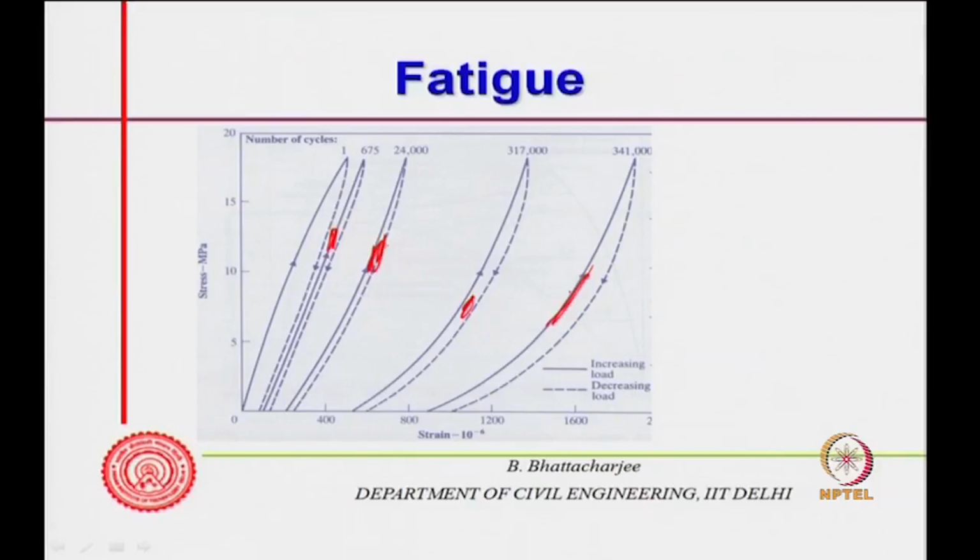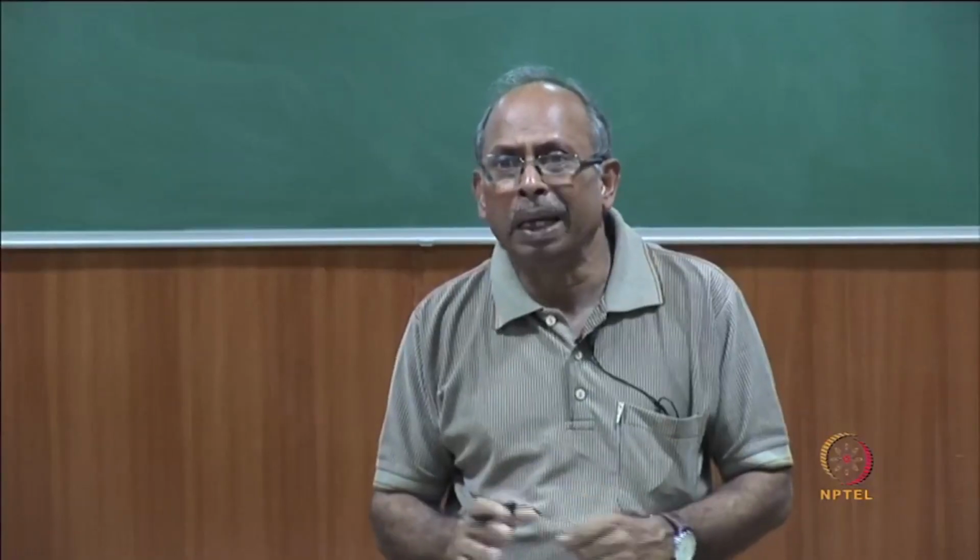What we will do is the fatigue, we have an introduction to fatigue I have given to you right now, and you can see that after a long period of time, because after long cycling, the number of cycles causes more micro cracks to appear. So, therefore, this increases. In the beginning there is a reduction, but under long cycling more micro cracks form under fatigue loading, because there will be friction and heat generation as it happens, or whatever mechanisms are there. So, fatigue causes failure in this manner.